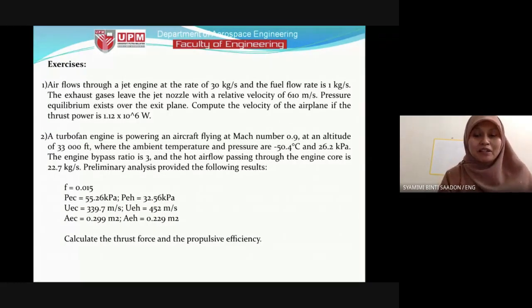So look here, as I've mentioned in my class the last two classes, the mass flow rate of the fuel is generally very, very small compared to the total air mass flow rate that goes into the engine. That's why sometimes, to simplify the equation of the thrust force, we assume that the fuel mass flow rate is negligible.